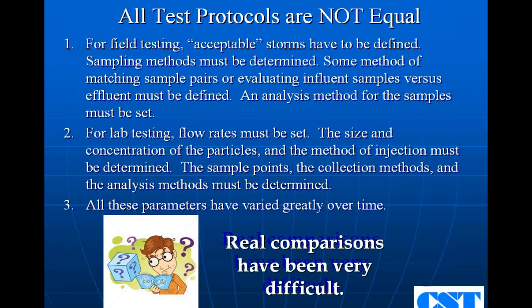And we used to think concentration in milligrams per liter was very important. We would test at 100 milligrams per liter, 200, 300. There is some variation when you get down to 100 or 50 milligrams per liter. But in reality, the concentration has a very small impact on the testing. So to save money and time, we found that one concentration of about 200 milligrams per liter is probably pretty good.